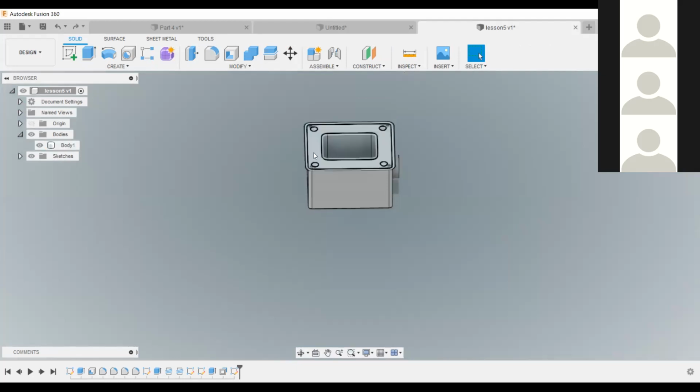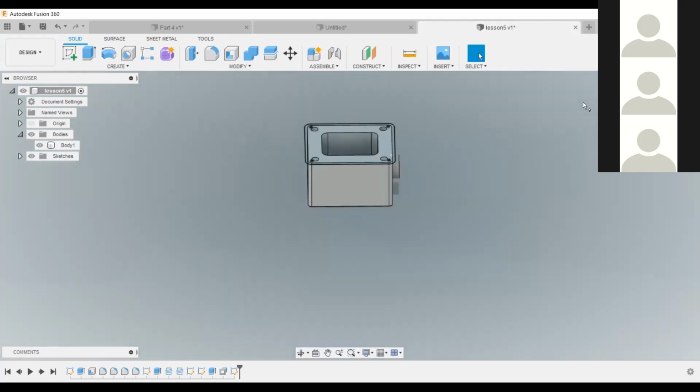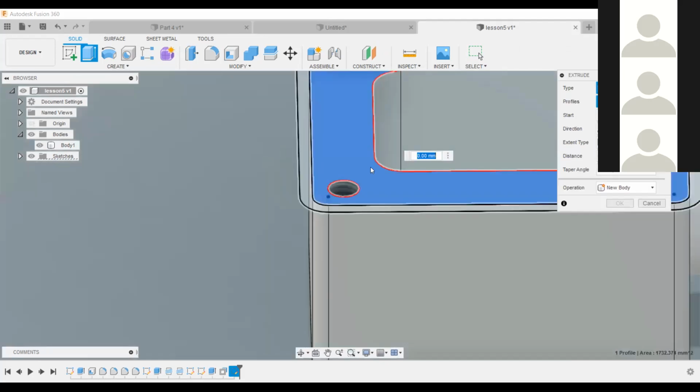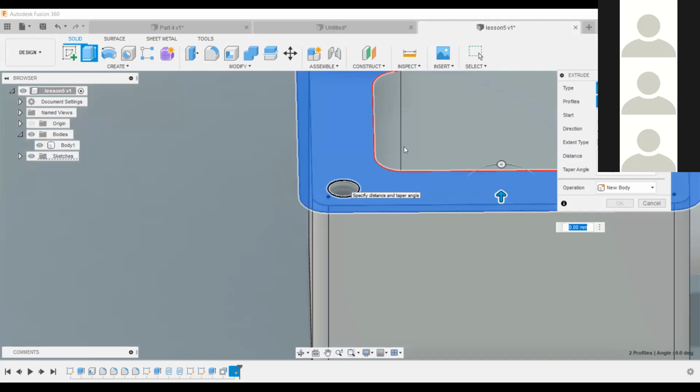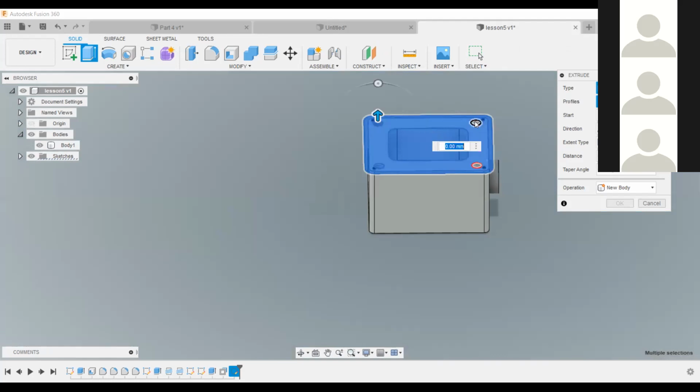So you click all those surfaces. You click all those. You extrude, just a minute. Then you click all that. You can zoom in, so you see, even these holes you drilled. All of them. Okay? And then we want to extrude for 3 millimeters. Then it will be like that.